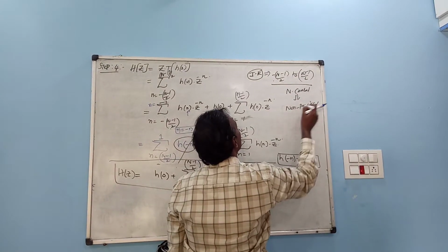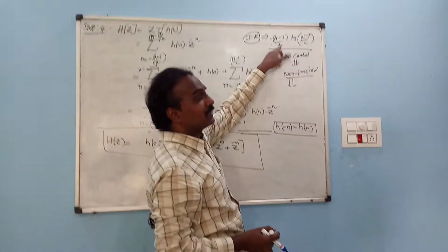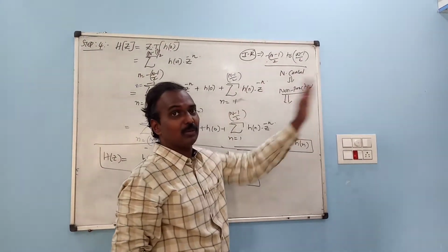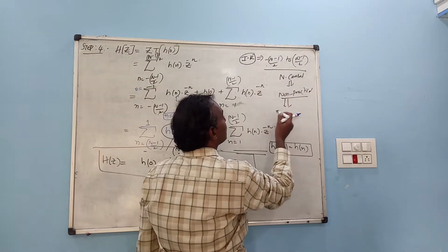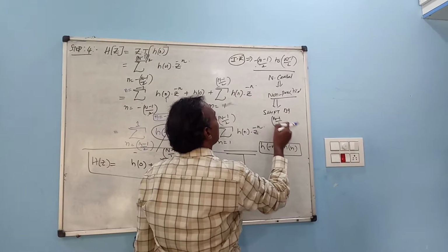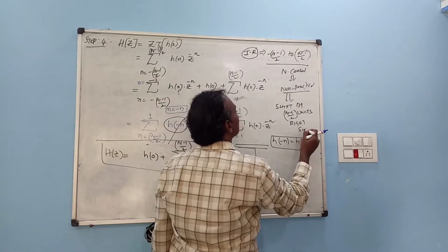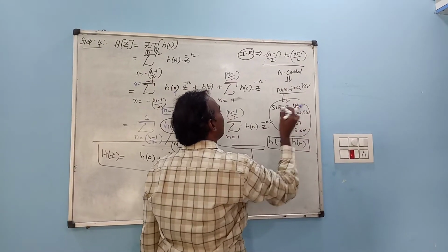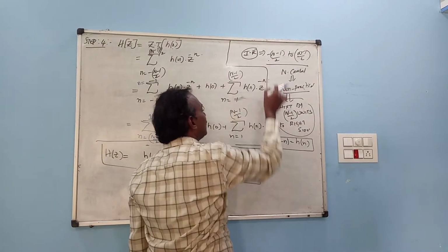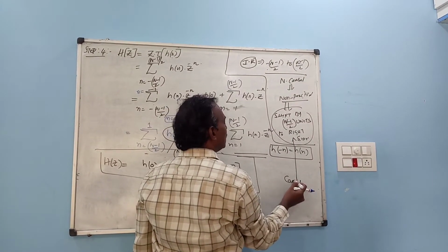So to make it causal, whatever negative limits are there, I am shifting to the right side. I shift by (N minus 1)/2 units to the right side, so in time domain I am shifting by (N minus 1)/2 units to the right side. Why am I shifting this here? We are shifting to make it causal. If I shift now, this becomes a causal system.